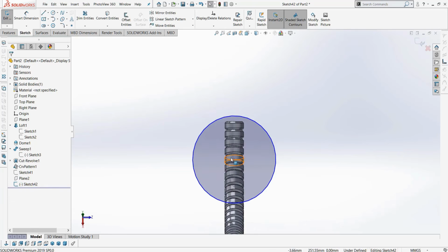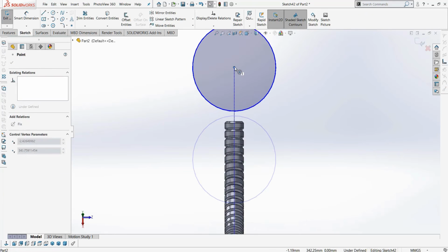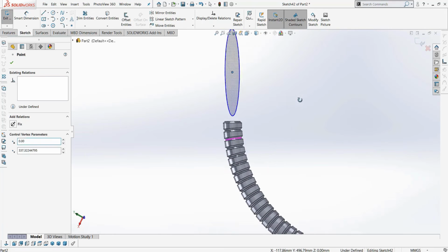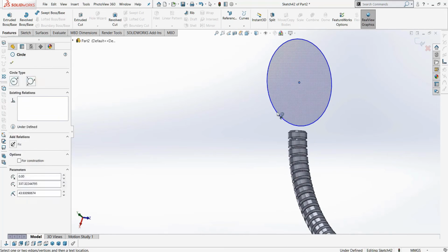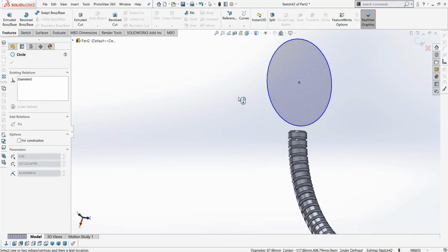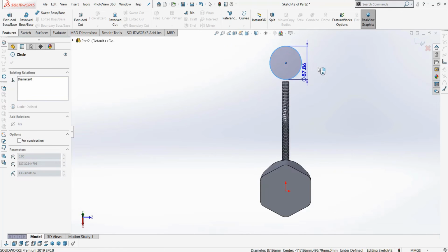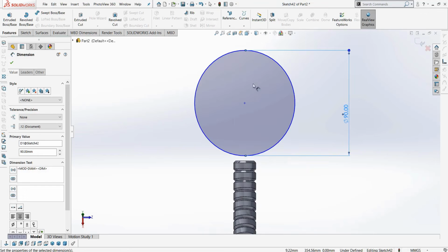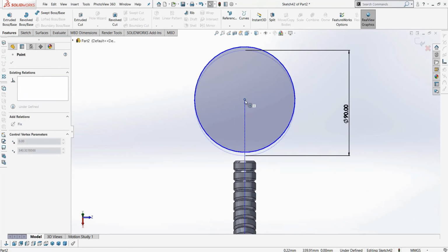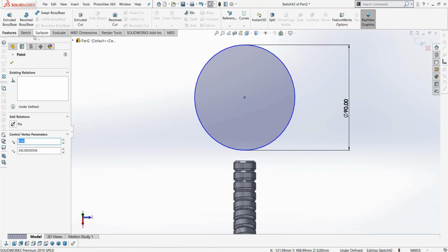Okay, I'll lift the center and bring it up to place it here so that it is tangent and actually aligned with the coordinate center. This position isn't bad. Let's give it a dimension of 90. I want it to have a ring shape, so I will use the offset from this circle.